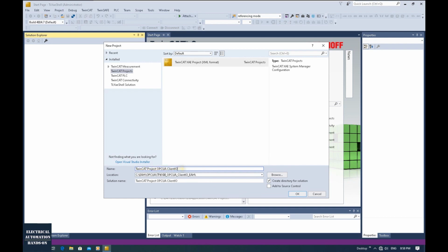Keep in mind, there are basically two methods to implement the OPC UA client in the Beckhoff system. One is named ClientIO. We use the configuration way to set up the client function. The other way is called Client PLC Open. Basically, we need to program the connection, send, and receive. I will use another video in the future to show how we can implement that. But personally, I recommend this way. After all, this is quite easy.